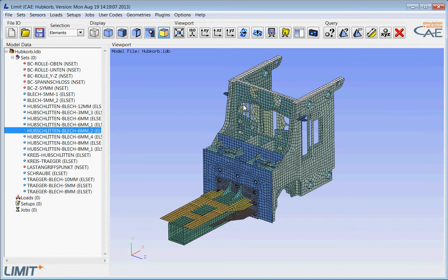And in the second assessment mode, which is called weld, we can take a detailed look into the local welding condition. We can define the orientation of the weld, we can define the local geometry of the weld, and calculate stresses for toes and roots, and make a really detailed fatigue assessment of the weld.